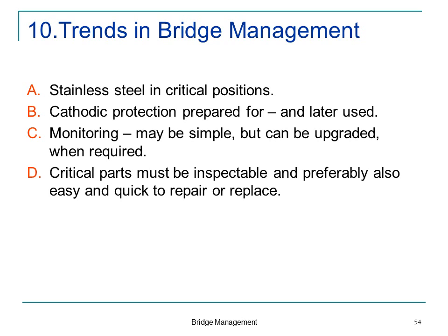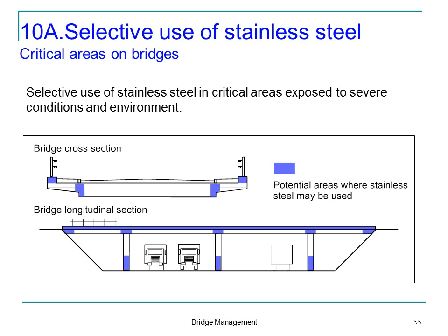Okay. Why don't we do all these things in every single project, in every single position? Well, mainly because they are expensive. And that's why we say, well, you build a bridge. You don't have to use stainless steel throughout the bridge. But it would perhaps be a good idea to use it in those spots where we know we normally get the corrosion.